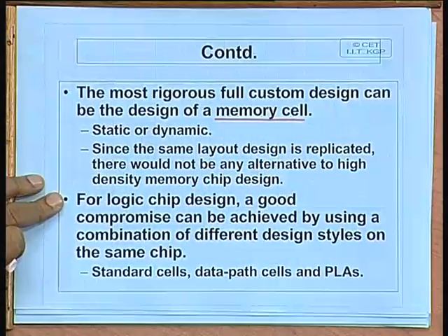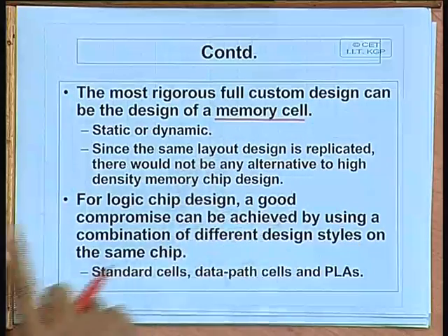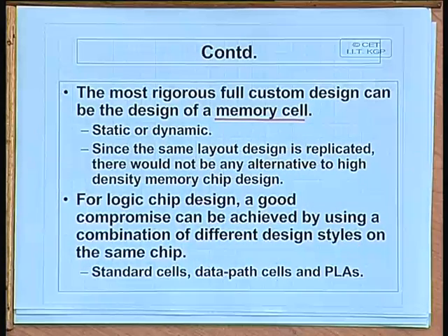So, one area where full custom design is used quite popularly is in the design of a memory cell. See, memory cell layout is very regular, but you want to design it in such a way that it is very highly optimized. So, in that respect, this is one candidate for full custom design.